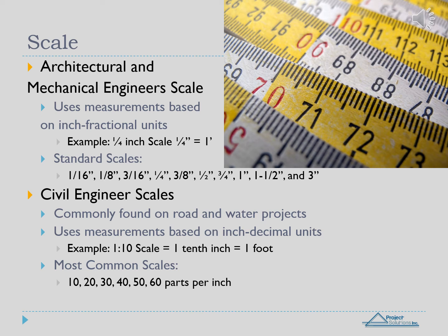Know the scale that you are using when doing takeoffs from plan sheets. For example, in an architectural or mechanical drawing, a 1/4 inch scale indicates that every 1/4 inch is the equivalent of 1 foot. A good set of 6-sided architectural and engineering scale rules will have most of the standard scales on them for manual takeoff. Also, make sure your plans, if printed, are printed in the correct size, or your scale will not be accurate.